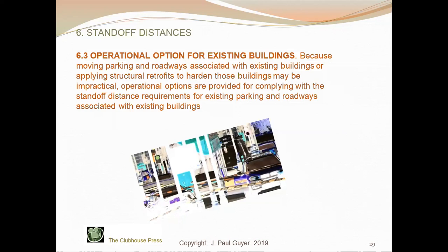And these typical operational options allow, for example, for establishing access control for authorized parking at the applicable standoff distances in tables B1 and B2, which you will see, in which case parking can be allowed to be as close as the minimum standoff distance to buildings without hardening or analysis.